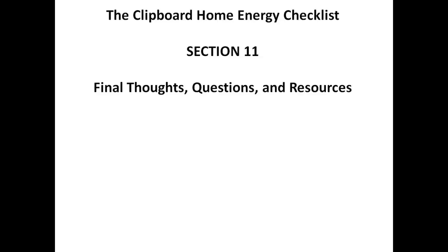We had a question about types of insulation, which ones are better and where you use which ones. Well, comparing styrofoam insulation to fiberglass or cellulose, those are the three most common types. Cellulose and fiberglass have a pretty close level of R value, and styrofoam has a higher level of R value, but it really depends upon the application as to where you use them.